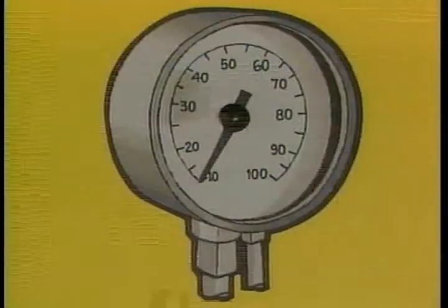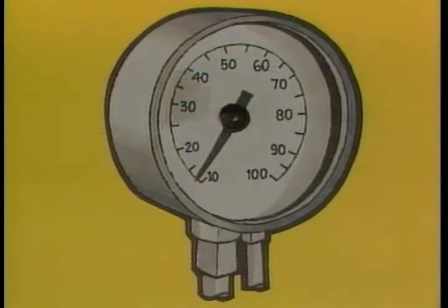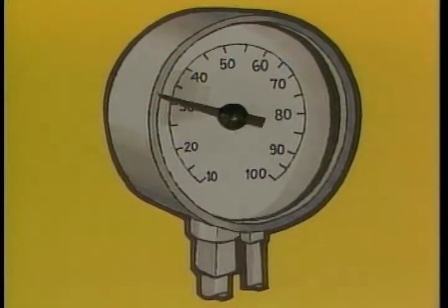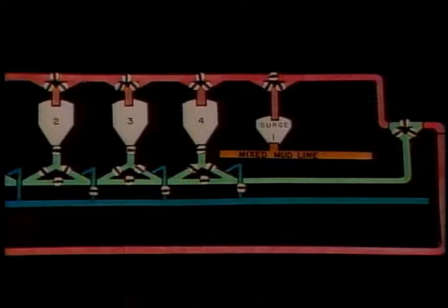An airflow is established between the two. Air, supplied by the air system, is blown into the bottom of the source tank. The tank has to be charged up to the operating pressure of the system before materials can be transferred, and this can easily take a half hour or longer. While it's charging up, you can line up all your other valves. Everything should be closed to start out.